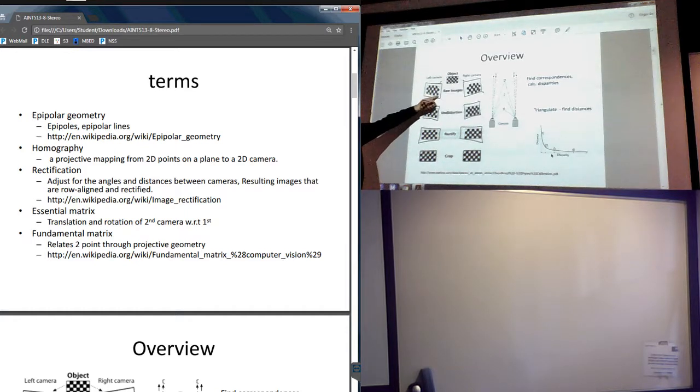The lens optics and the positioning of the sensor need to be corrected for, and we can do that by comparing the left picture with the right picture and linearizing what we know to be corners in each camera in isolation, so that we can correct for any geometric distortions in each camera. Once we've done the correction for geometric distortions, we can then rectify the two images in our stereo pair.